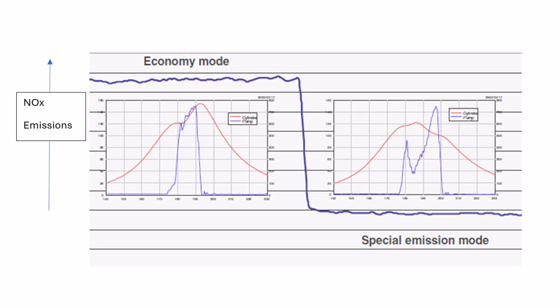As I told you, nitrogen is an inert gas. It does not react with the oxygen. It reacts with oxygen only when pressure and temperature are very high, as they occur during combustion of the fuel, because it's an explosion, very high temperature. If you can lower the temperature a little bit, lesser NOx emission will be produced. That is what is being done in emission mode.